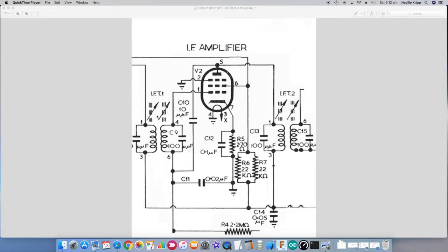Now, both of those are going to be tuned to around the 455 mark. In some cases, you will tune for a peak around 455 kilohertz. And in other cases, you may need to extend the bandwidth, so you may tune one side so that its peak is slightly lower than the IF frequency, and you may tune the other side so that its peak is slightly higher.